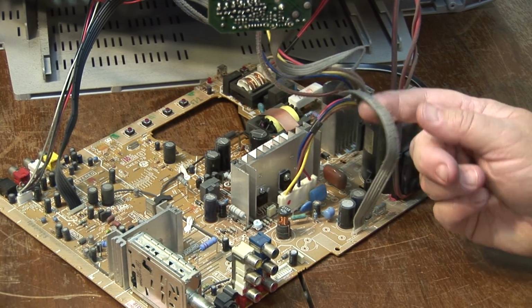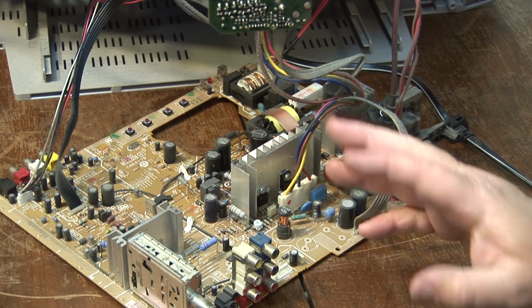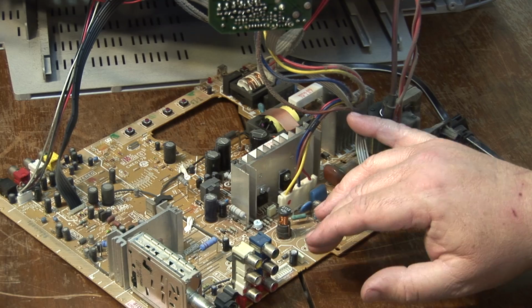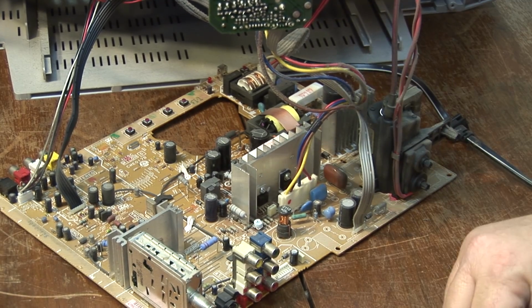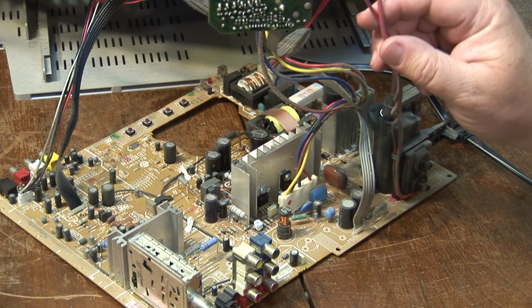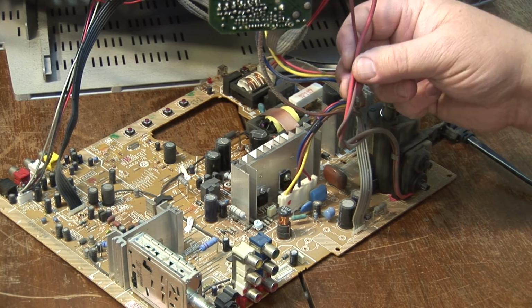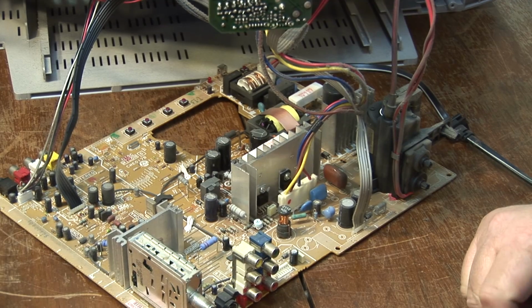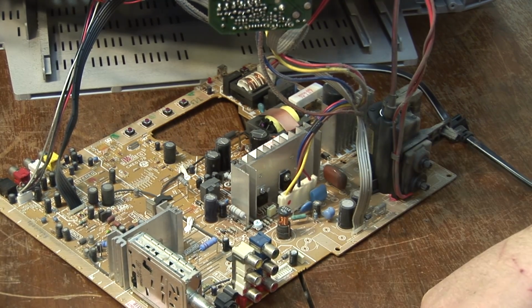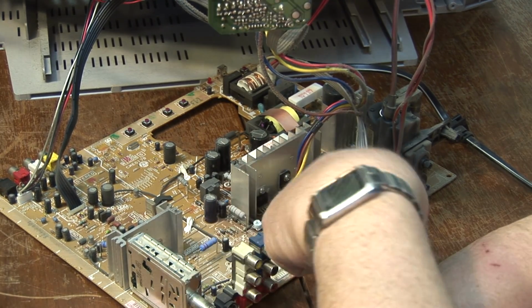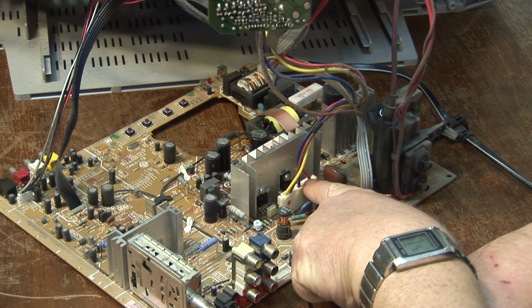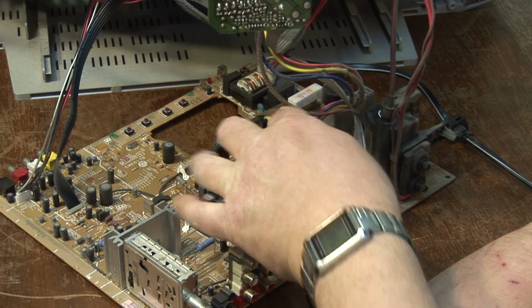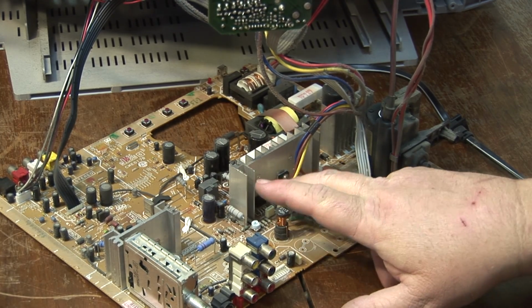And here's our interconnect to the CRT that sends our video signal and our screen voltages and so forth up to the neck of the CRT. Our high voltages for focus and screen come in on these 2 red leads that come right off of the flyback transformer off the focus screen resistor. This is again our horizontal linearity coil. Our horizontal coil is typically going to be the red and blue wires, and that's why they're separated, because there's about a 1,000 volt pulse on here, and our yellow and brown wires here, these are going to be our vertical, which go to this side of the plug.